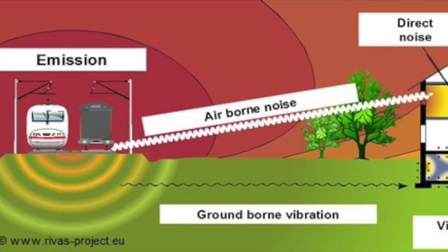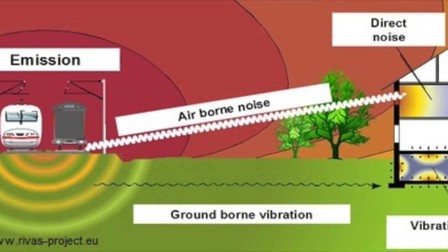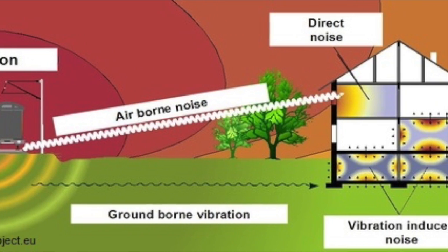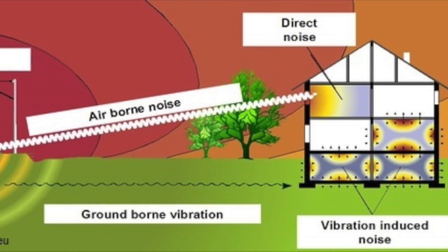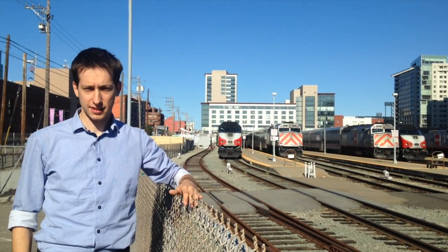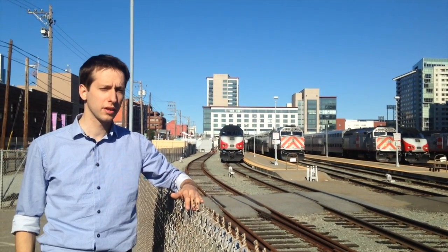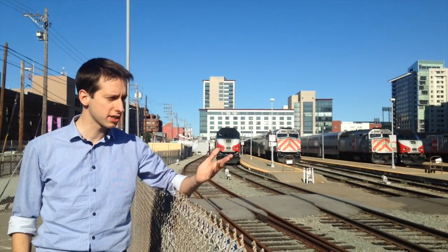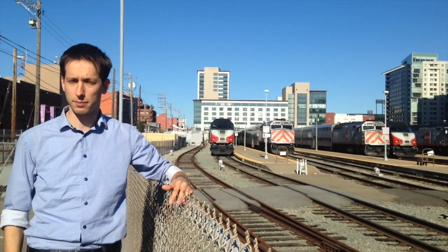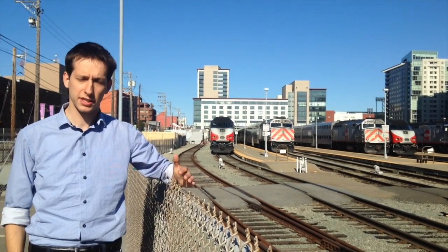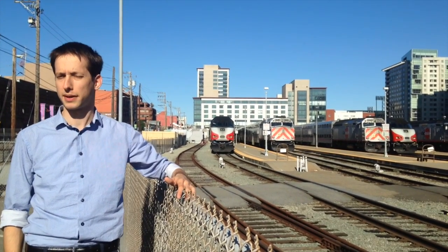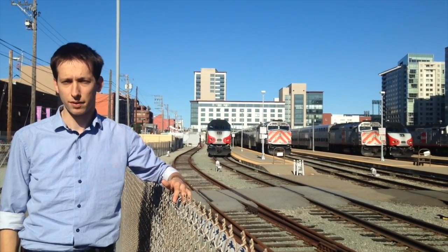Increasing public sensitivity to noise and vibration calls for efficient vibration mitigation measures. The high cost of such interventions requires the use of state-of-the-art numerical prediction models. For existing railway tracks, the most efficient strategy is to intervene on the propagation path between the source of vibrations, being the railway tracks, and the receivers, being the residents of nearby buildings. The main advantage is that no modifications to the track are required, while multiple buildings can be protected simultaneously from vibration.